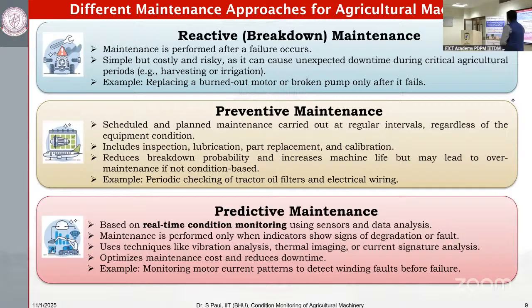So what kind of maintenance work do we normally prefer? The first one is: jab sab kharab ho gaya, tab karo. That is breakdown maintenance, or reactive. When any equipment stops working, at that time we invest in it to rectify all the possibilities. Then comes the second one, that is preventative maintenance. It is costlier. When everything is running properly, even then you periodically do the maintenance. That is very lacking in our life, but still that is desirable.